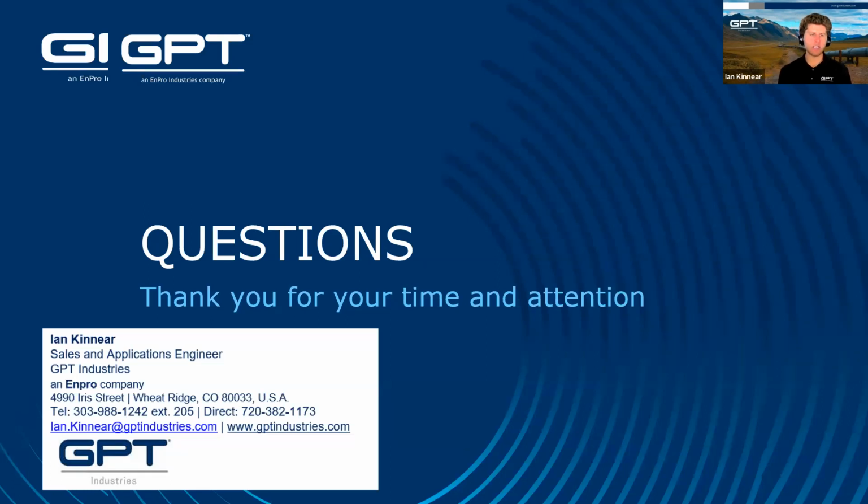I'll reach out after and talk some more about this and share some things with you. It is something that we see more and more, and it is a challenge, where the media is conductive enough that it's passing the current through the pipes. Your isolation kit is working as intended, but the media is passing the current. It's something that we are aware of, and I can share some more with you, but those are some of the solutions that we've worked with.